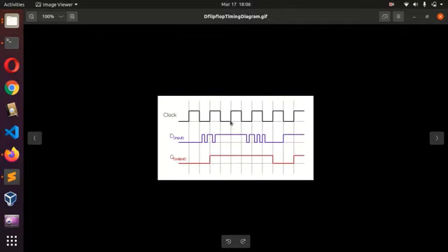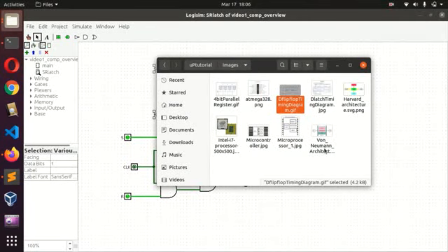And the same thing just goes. So on the rising edge, whatever is on the data line will appear on the output Q, and at the other states of the clock, it will not follow, only on the rising edge of the clock. So yeah, I think that's basically how latches and flip-flops are.